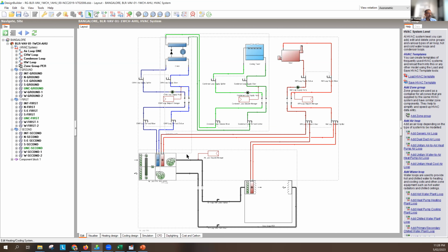And then you can look at the variation of the cooling energy across the year, and you may be able to pick two chillers, two sizes, where they run at their optimal parts, and you'll see the energy use drop. You won't see the cooling load change very much, but what you will see is that your pumps and your fan energy start to reduce when you optimize these sorts of things.